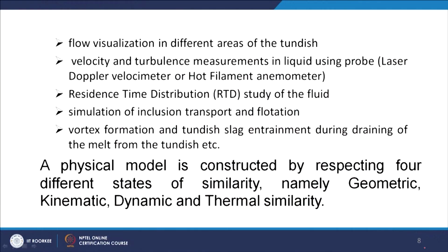Velocity and turbulence measurements in the liquid using probes. As the flow inside the tundish is normally turbulent, you can measure these velocity and turbulence quantities in the tundish, or in any vessel, using proper probes, like a laser Doppler velocimeter or a hot filament anemometer. These are basically turbulence measuring instruments that can be used.